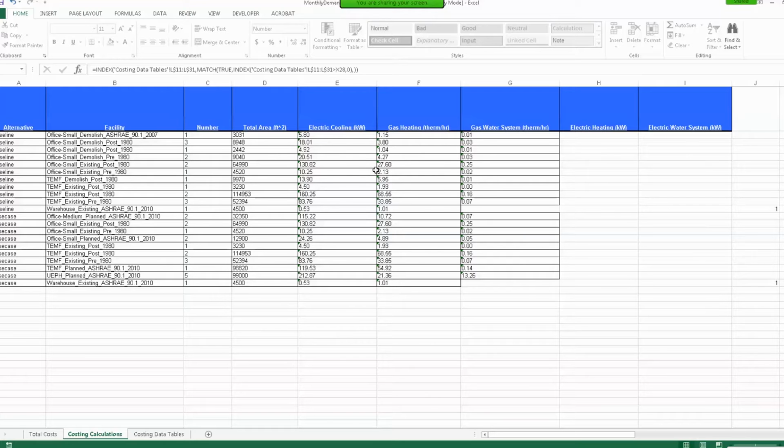And these are the peaks that we wanted to look at, and we're using these peaks to cost out the decentralized equipment. So the boilers and chillers that would be needed to meet these peaks, to do the cooling or the heating for the building, and similarly the domestic hot water. So there are potentially 5 categories. We've got cooling that's done electrically, gas heating. It could be like a boiler system. Gas source for domestic hot water. These two, again, would be the most common.